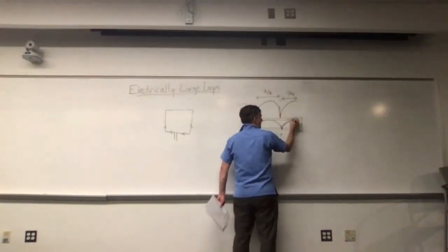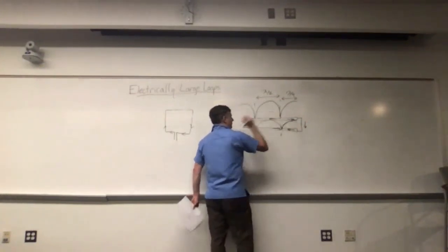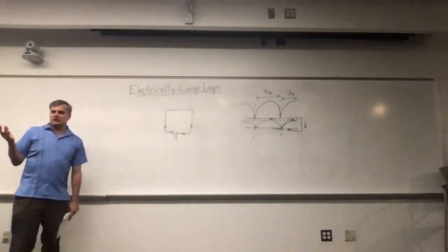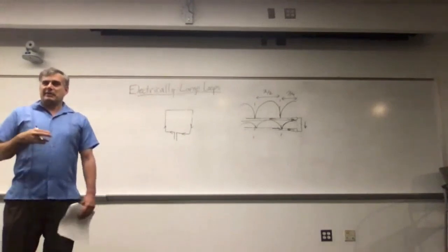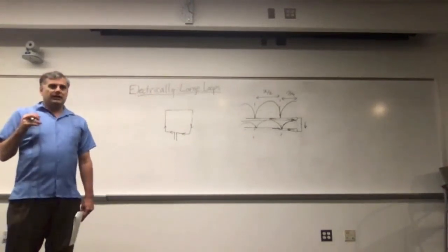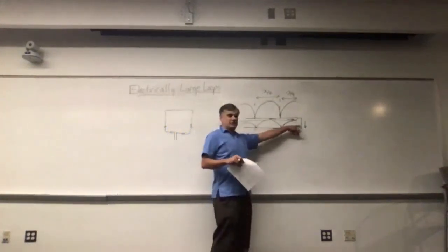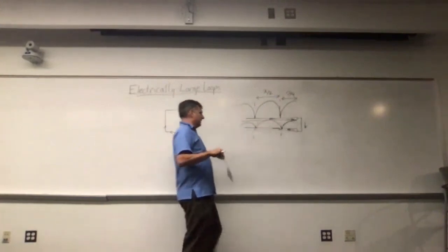And this polarity of current is going through here, down through here, and then I get polarity reversals when I traverse the null. That's just back to the very first couple weeks of class, when we reviewed transmission lines, standing waves, and came up with the solutions. We've been doing this all class period long. The only difference is that I shorted this instead of opened it, so that means I'm at a peak instead of a null at the end.